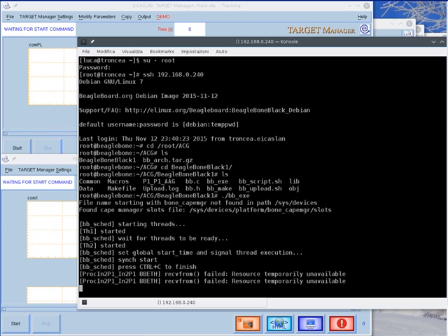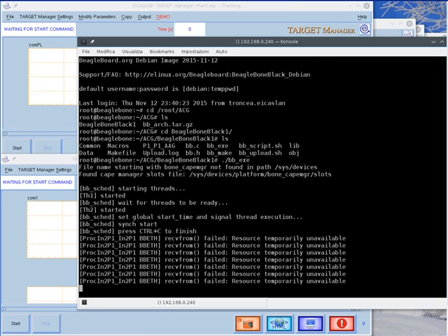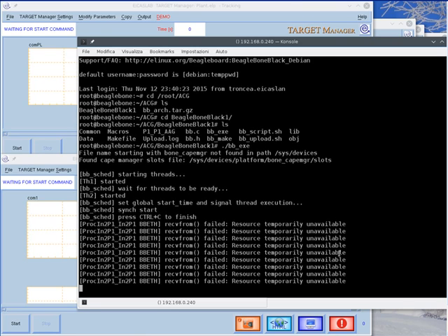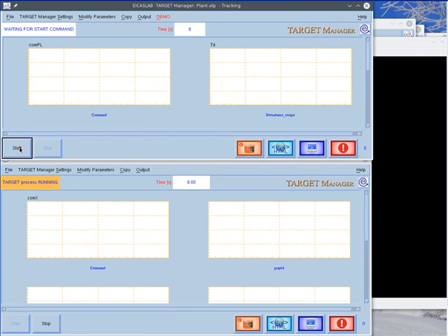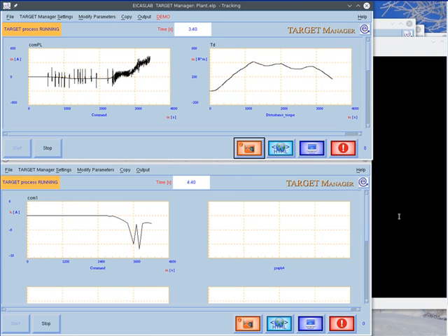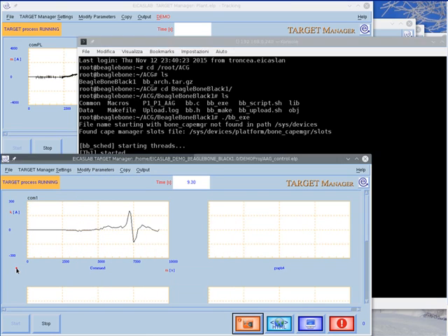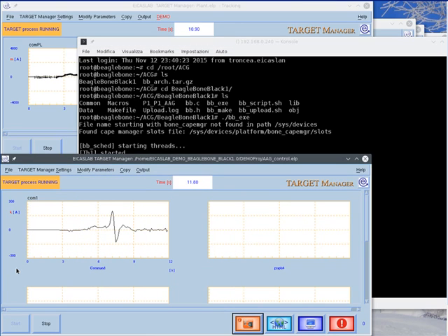Now the control application is running, but it doesn't receive any measure, so the standard output prints a periodical reception timeout. Start now the monitoring process and the plant emulator. The trial now begins. There are no more periodical reception timeout, and the plot areas show in real time a set of significant signals. In standard final validation test trials, we have not the graphs of the plant, but we have always the graphs of the monitoring system.